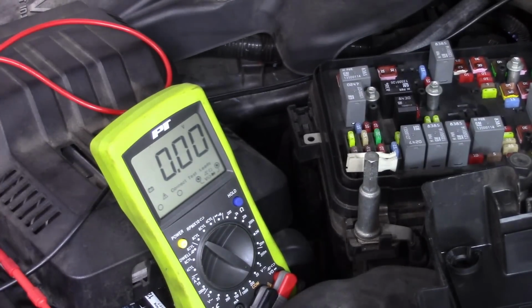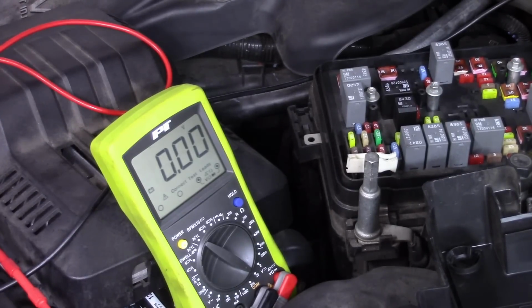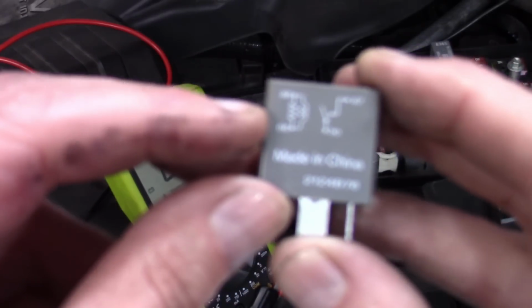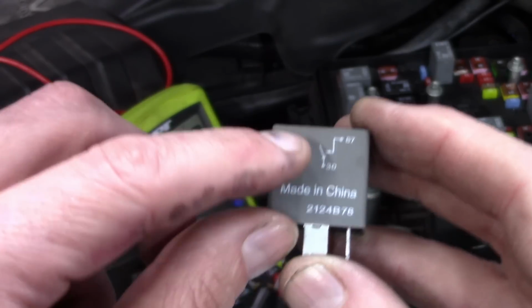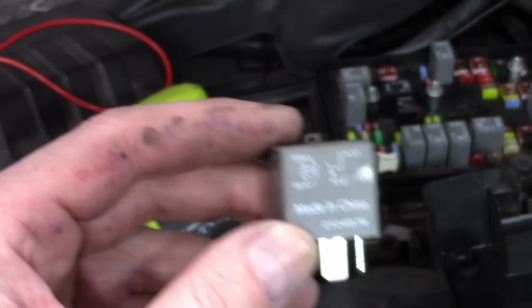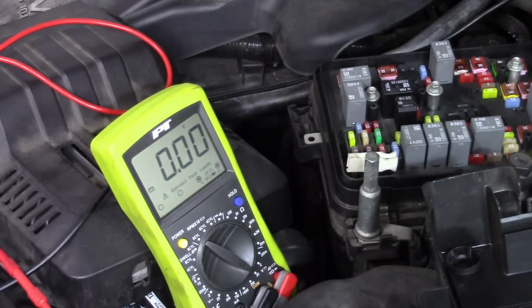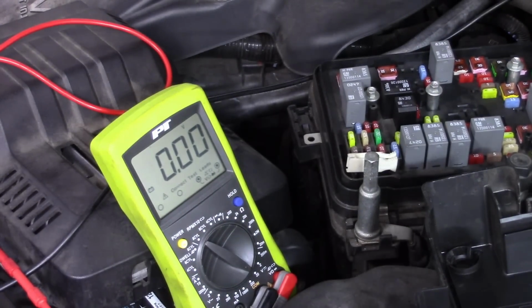All right, now, extremely important. Do not ever do that unless you know exactly that you are on the load side. If we do that on the control side, we would be bypassing the load. We would create a short circuit. We could permanently damage that circuit. If we're lucky, we blow a fuse. If we're not lucky, we might blow a computer.